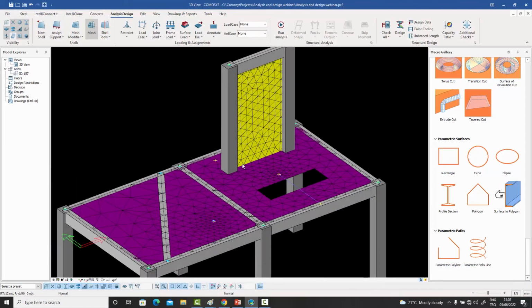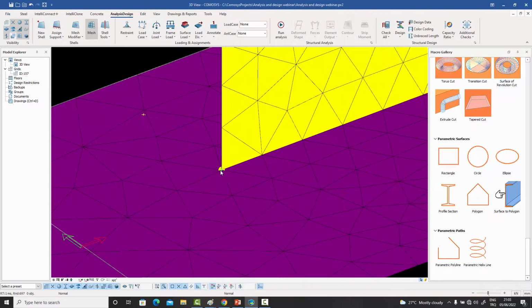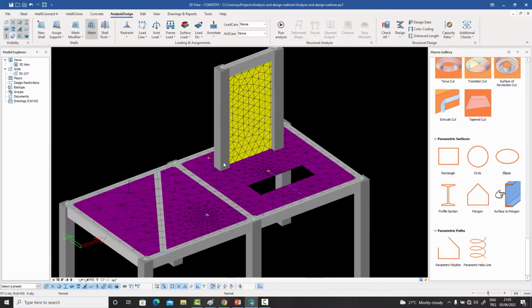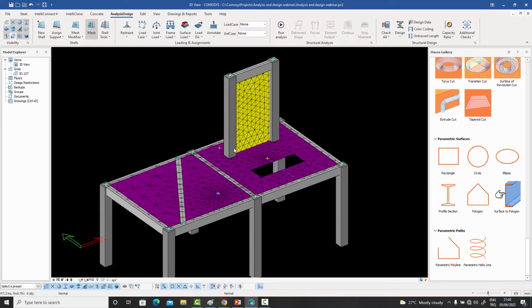And if we were to convert this into line mode, you will see that the columns are landing at a point which is an exact node point for the supershells. So what we have is exactly what we would have done by hand. This would have taken us hours to do. And you can probably already feel the kind of advantages this supershell meshing is going to give you.